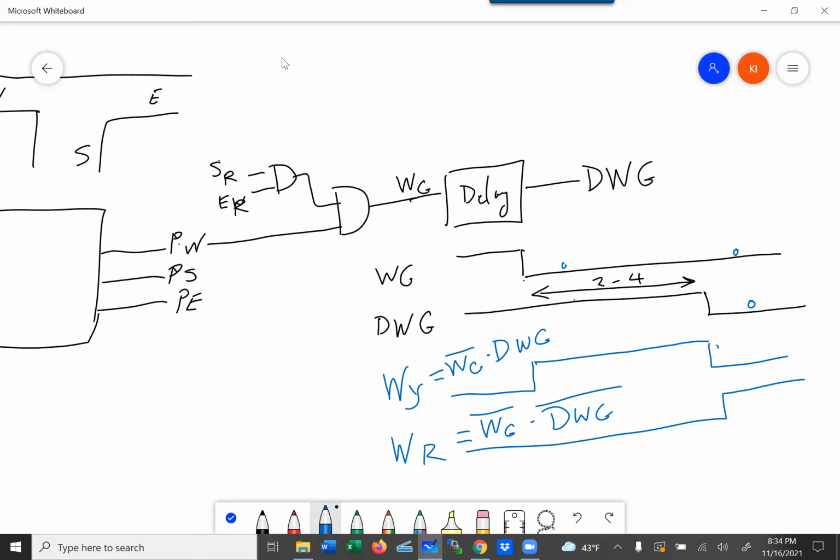Once you've got this lane done, you can start creating the same setup for the south and for the east, and you now have a set of three-way intersections where the green comes on. When the green goes away, yellow for that line comes on, and before anybody else can go green, you have to have the red come on, and then they can go green. This way you avoid any kind of accidents and all that kind of stuff.